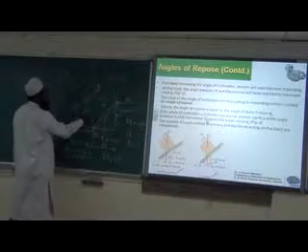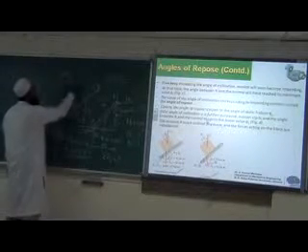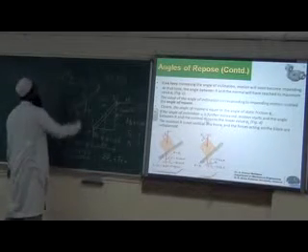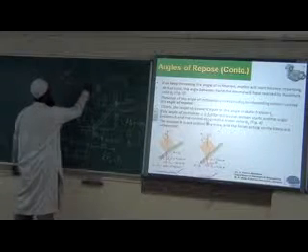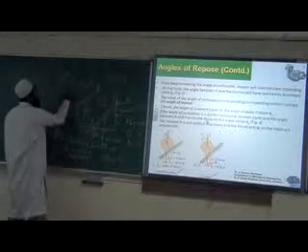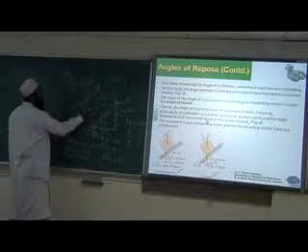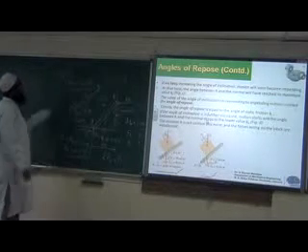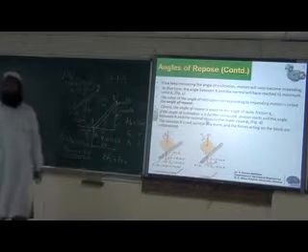W into this distance, which is 4, then FF into its perpendicular distance, 6, minus NF into 8 equals 0. From this, W is known, NF is known, FF can be found.